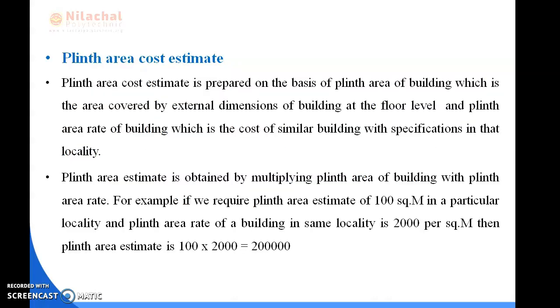Okay. Next, we discuss plinth area cost estimate. Before going to plinth area cost estimate, first we should know what we mean by plinth area. Plinth area is the total area covered by a building from ground level. So, plinth area cost estimate is prepared on the basis of plinth area of building, which is the area covered by external dimension of building at the floor level, and plinth area rate of building, which is the cost of similar building with specification in that locality.